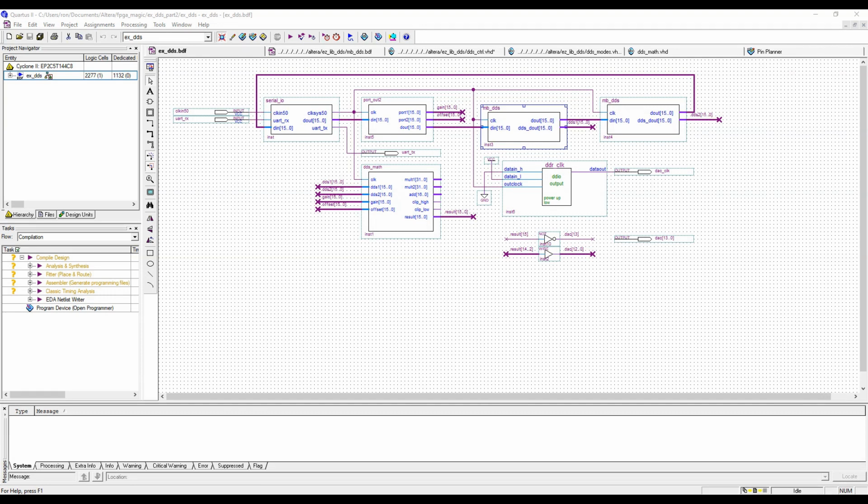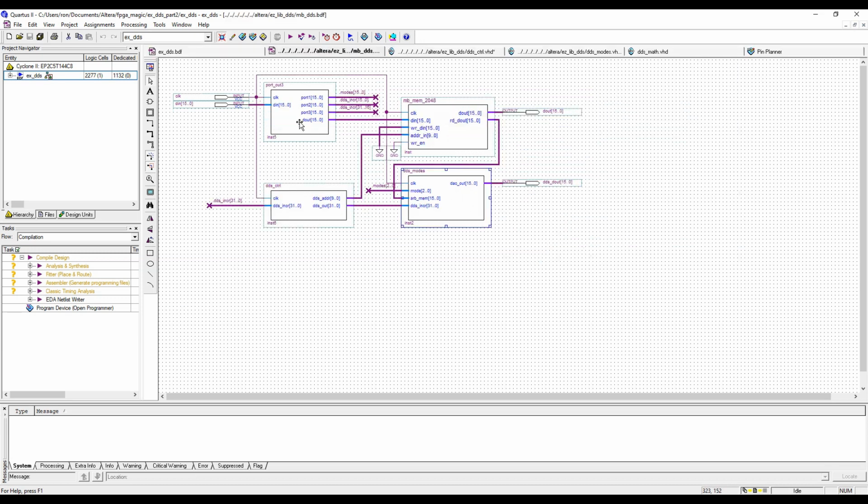The FPGA design is like magic because we use pre-made macros. The serial port is used for control. A 2-output port is used to control the gain and offset. There are two function generator modules in here. Each one consists of two ready-made modules, a 3-output port that controls modes and frequency.